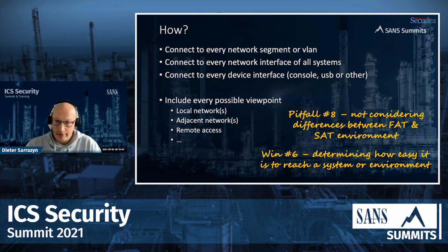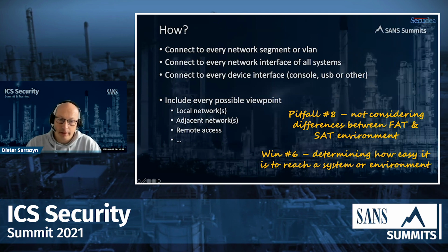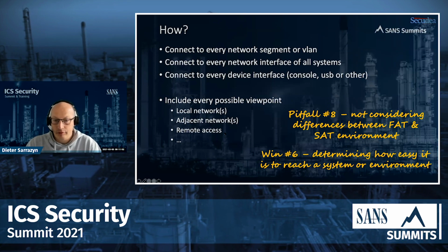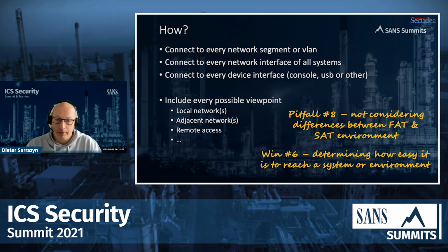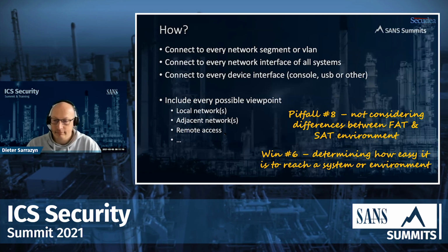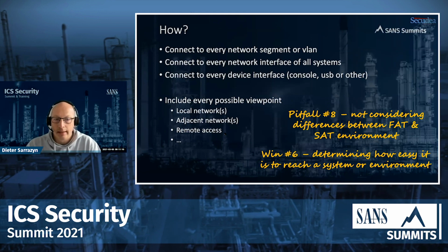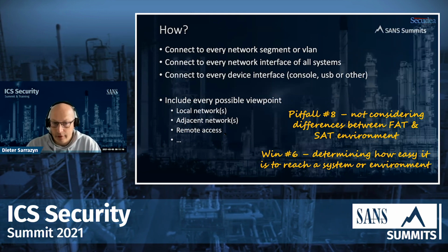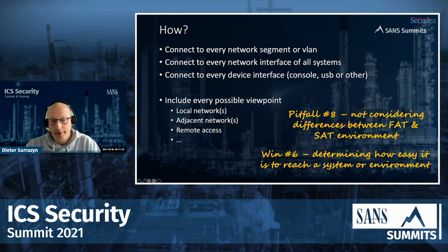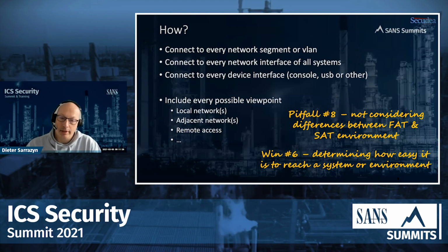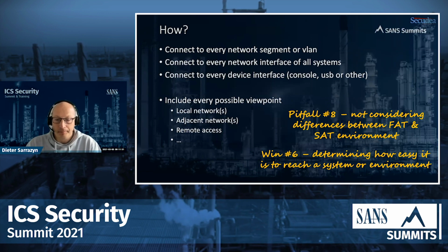One of the pitfalls I mentioned here is that you do not consider differences between FAT and SAT. It's often the case that in the FAT environment, there's a certain remote access for the vendor to have an easy view on the FAT environment, but the remote access in SAT is through the organization's environment or through DSL or whatever. And if that's forgotten, that might be an easy way in for attackers, of course. A win here, I found that a win at least, is determining how easy it is to reach a system or environment if you take all different viewpoints into account.